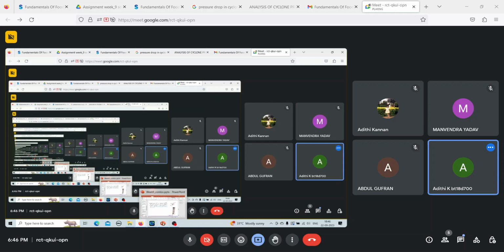So in this case, Fc is equal to m omega square r. I am taking a differential. So for a small region in the centrifuge liquid, which is of a mass dm, it experiences a centrifugal force of dFc. So dFc is equal to dm into omega square r.